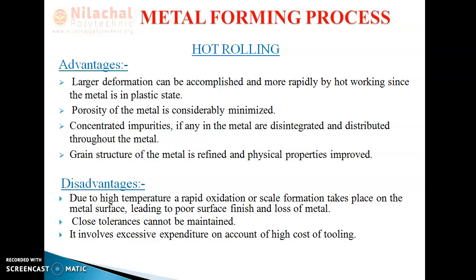Already we will discuss in this point what hot rolling means. If the work material is heated to its recrystallization temperature, and thereafter we put the work material in between the rolls, it is named hot rolling. And if the workpiece is not heated, that means at atmospheric temperature it is put in between the rolls, then it is simply termed the cold rolling process.